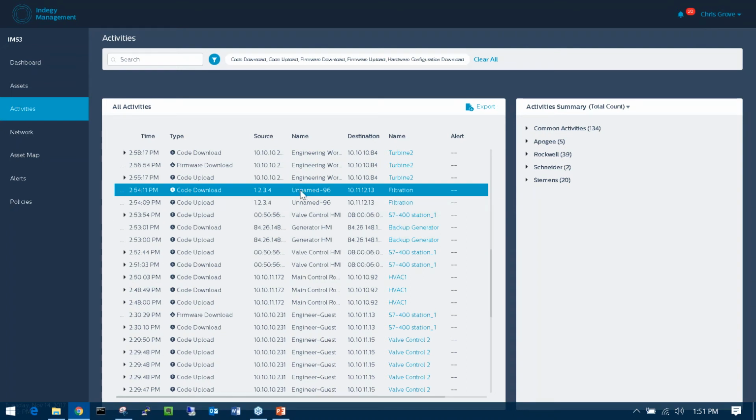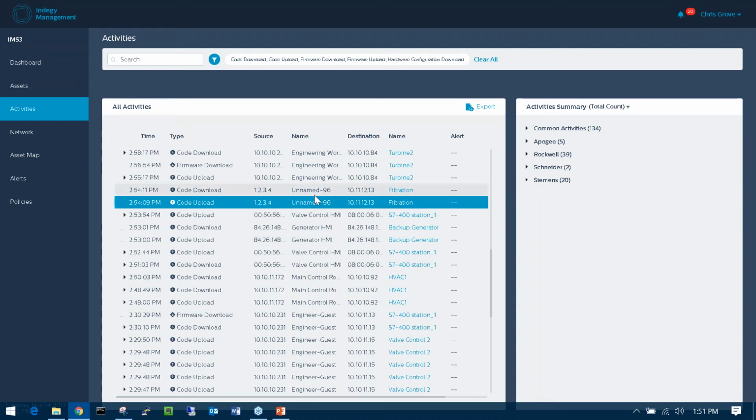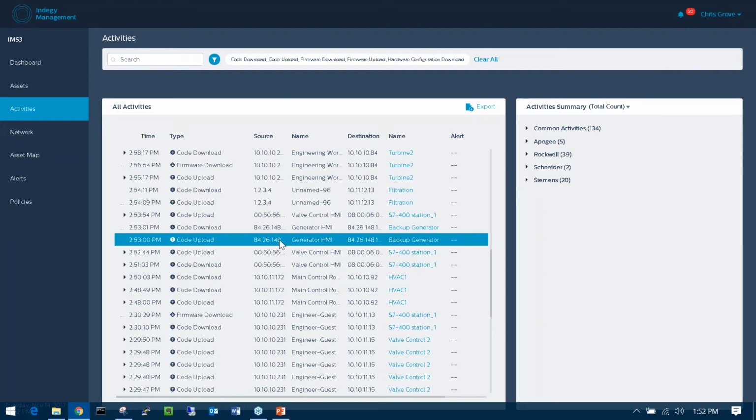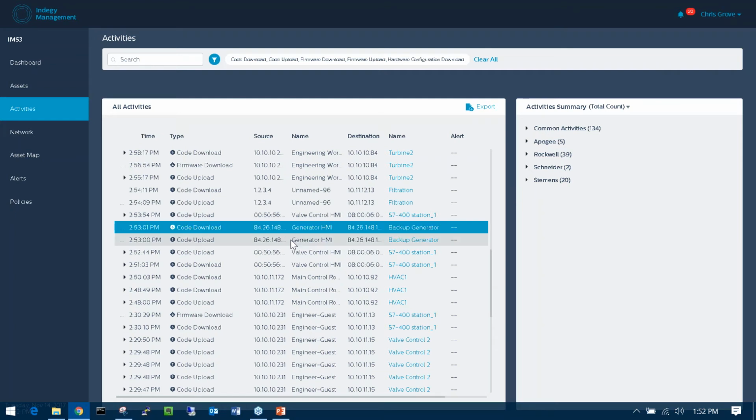And as I'm looking at the unnamed machine that we're chasing here, I'm also starting to see indications of an HMI that is doing these types of operations as well. I should have HMIs. Remember, these are the panels. They're only usually configured to do a very strict set of operations. They only have dials and buttons and things that you could push that send commands to the PLC, but they're never used to rewrite the firmware or update the logic of the device itself.